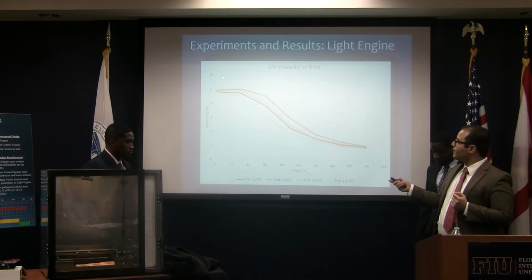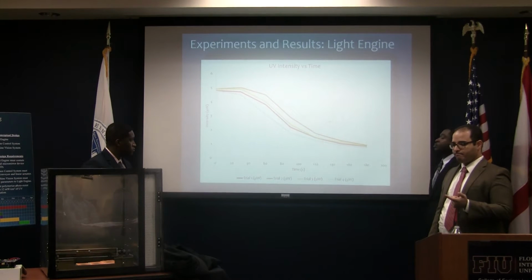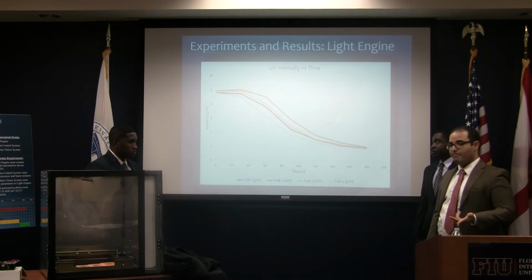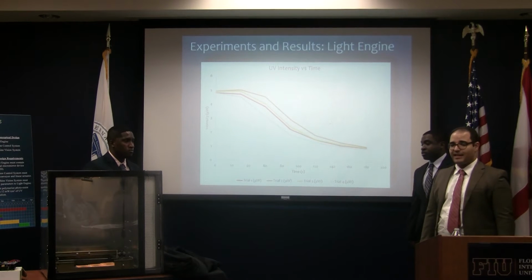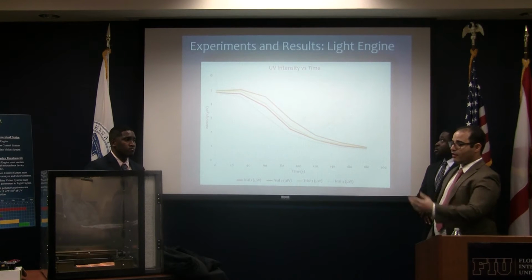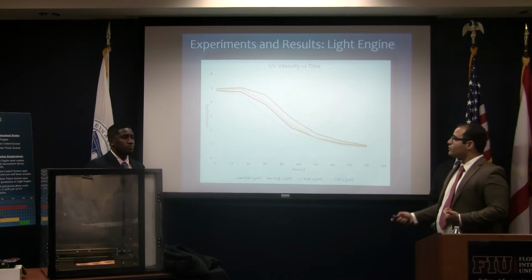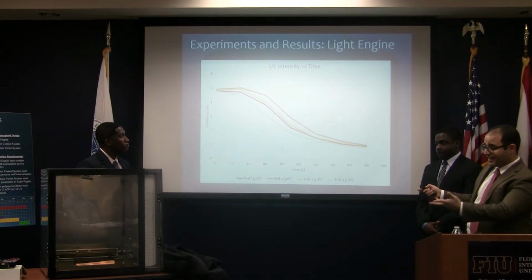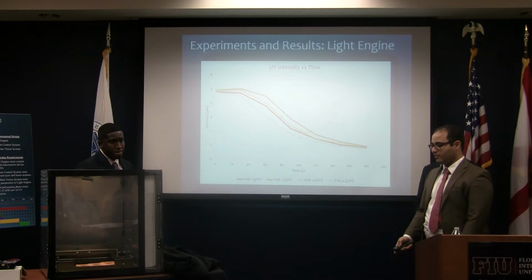So what about this 5 microwatts? What will that do for us? The required material requires 12 milliwatts. At 5 microwatts, that would take over 40 minutes to expose. But then after the experiment, we found out that the photodetector is calibrated for 400 nanometers. Thus, our 385 nanometer LED was out of its range. So what we suspect was actually recorded or detected by the optical detector are harmonic frequencies emitted by the optical engine.